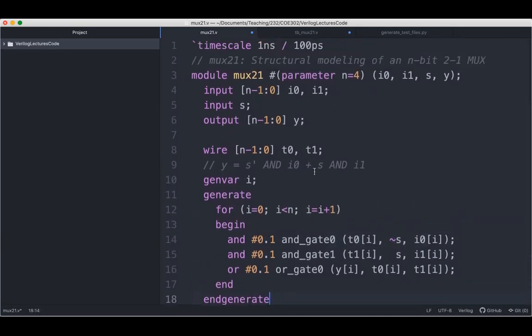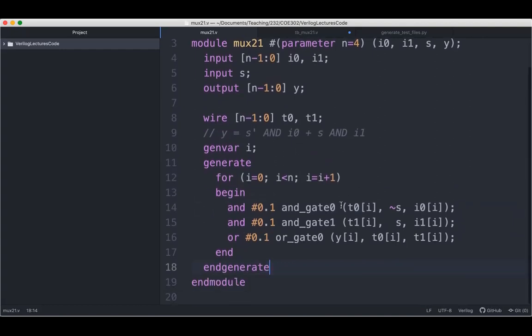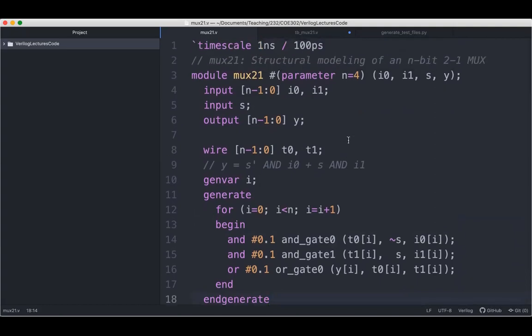Okay, if no questions are there about this module, I think we better look at the test bench for this case. For this course, we are going to create what we call comprehensive test benches: a test bench that tells you whether your circuit matches a golden output, a ground truth. We have a file that contains the ground truth.